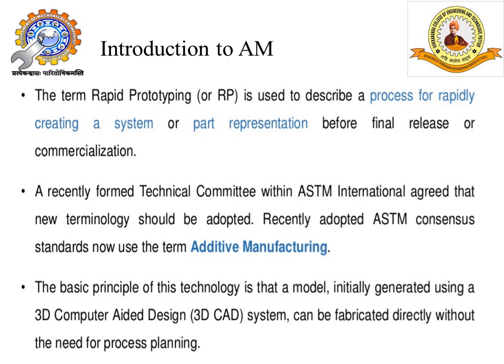Many of the pioneers proposed the use of structured lighting to create contour lines of an object photographically, then using these lines to cut and build the object from sheets. In 1956, Munz patented a layer manufacturing system for fabricating the cross sections of a scanned object by selectively exposing transparent photoemulsion. The system produces layers by lowering the position in a cylinder and adding appropriate amounts of photoemulsion and fixing agent.